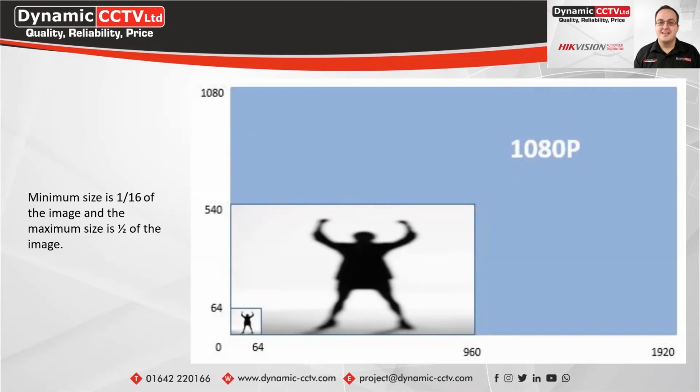With the DeepinMind NVRs, if it says that it's a 16S model, that means it has 16 channels capable of the false alarm filtering, but that is at 2 megapixel resolution. If you use 4 megapixel cameras, for example, that would be reduced to 8 channels of DeepinMind Analytics on the NVR, and then it would be down to 4 at 8 megapixel resolution on the cameras.